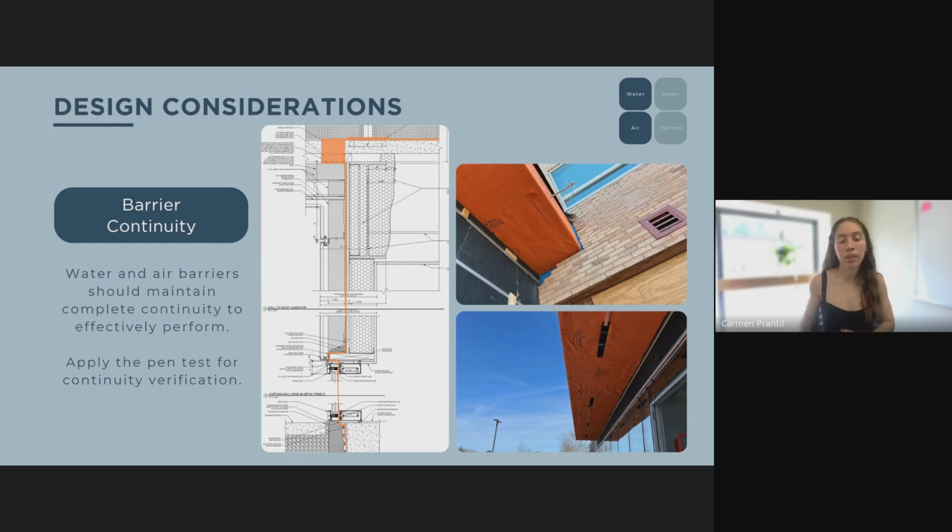If we look at this detail that we've shown here, we can see, again, we've traced our air barrier in orange. This detail is this wall right here. They essentially just hadn't installed the cladding when I took this photo, but we returned the air barrier behind the exterior insulation. And this soffit is in this detail just beyond, you see the break line here. So is there any reason why we wouldn't have just wrapped the soffit in an air barrier membrane?